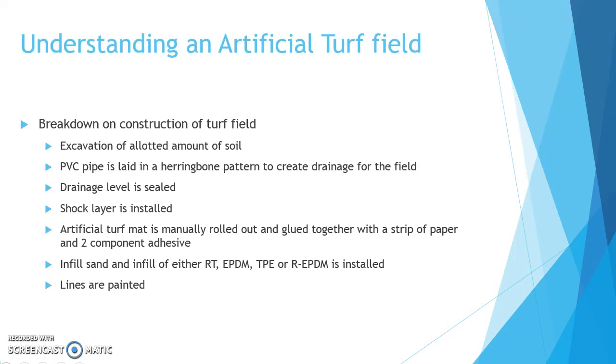The second step is to lay the PVC pipe for the drainage to the field. The herringbone pattern is just the simple setup that they use to allow for runoff on the field and allow that field to drain properly.